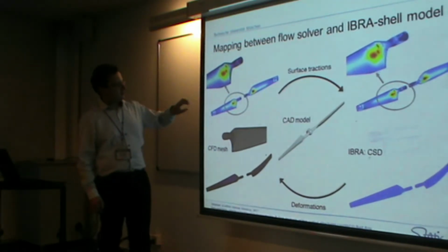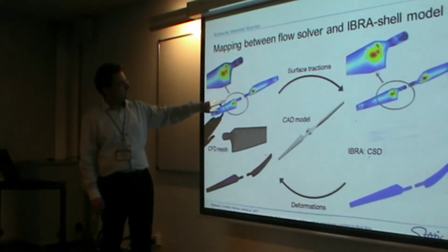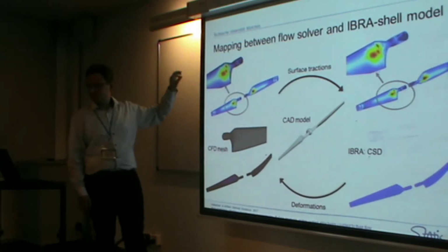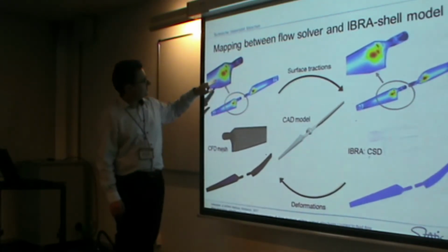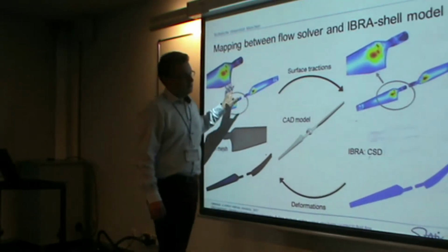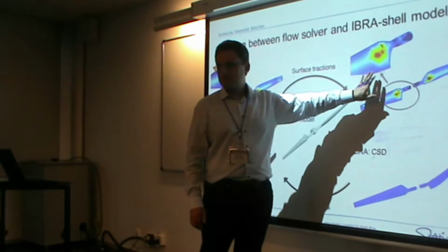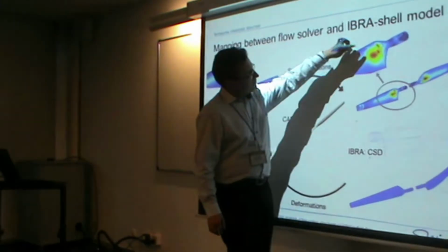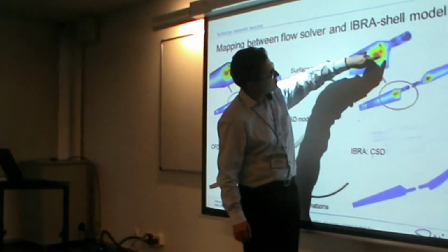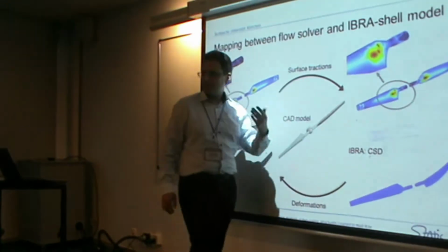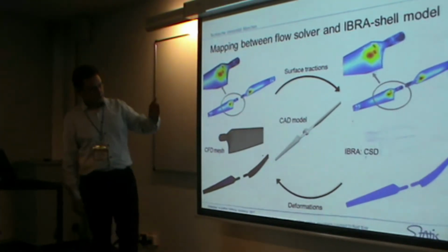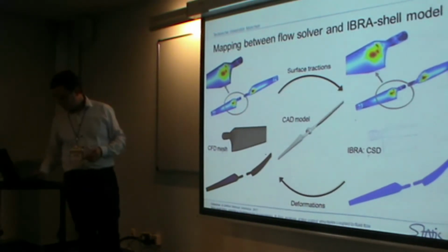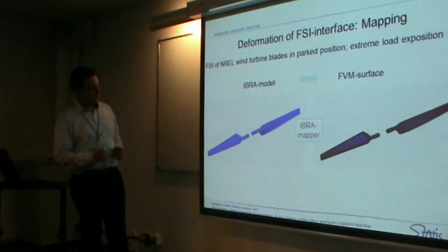The message is, that's just the onset of the flow, we see here some kind of pressure bubbles. This is the finite element solver on the top with very fine resolution. You see here these small features in the pressure map. This is for a specific time step, and that's on the isogeometric B-Rep analysis discretization. We see that these features, even small features, and what we are proud of is even crossing these patch connection lines, are mapped nicely. That's something which is really working very well. And also the deformation mapping, but that's something I've shown to you before already, this works. So the circle is closed, and we can go for these visualizations.